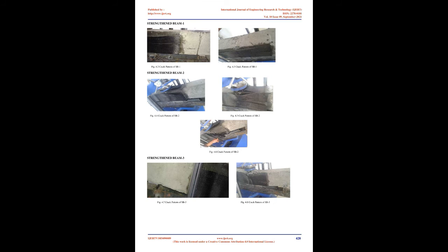Mixing of concrete. Mixing of concrete is done thoroughly by hand mixing. Compaction. All specimens were compacted by tamping rod, and sufficient care was taken to avoid displacement of the reinforcement cage inside the form work. Finally, the surface of concrete was leveled and smoothened by metal trowel. After 7 hours, the specimen detail and date of concreting was written on the top surface to identify it properly.